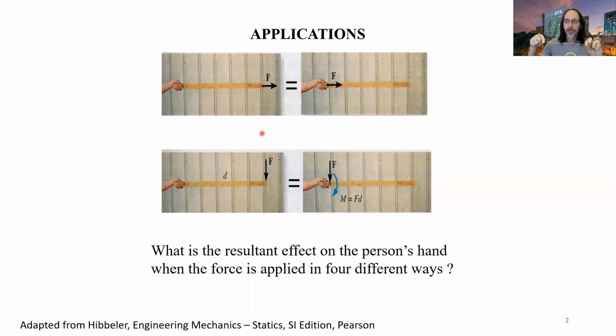However, if I apply a force here, downwards, if I apply the force here, I can just have my thumb. Right? So if we work back the other way, if I apply the force downwards, I can just have my thumb underneath to resist that. But if I tried to move that force out now, right, clearly you know that that's going to just rotate and fall off the support here. Right? So in moving the force from here out to here somewhere, I've had to do something different at the support end of the stick, right?